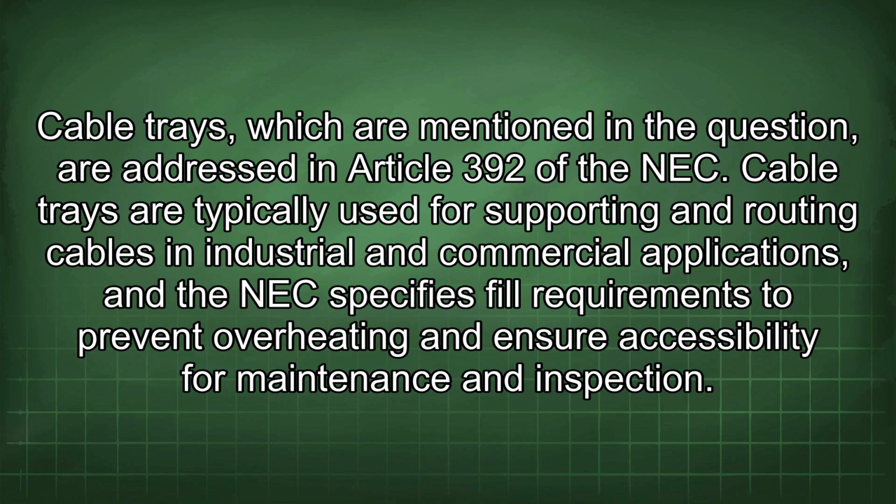Cable trays, which are mentioned in the question, are addressed in Article 392 of the NEC. Cable trays are typically used for supporting and routing cables in industrial and commercial applications, and the NEC specifies fill requirements to prevent overheating and ensure accessibility for maintenance and inspection.